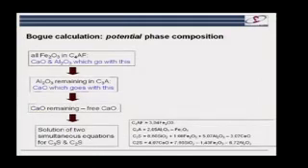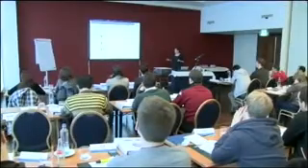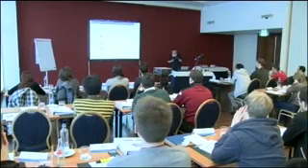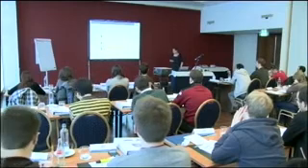And you can express that all in these very complex equations, which take into account the different atomic weights of the different things and everything like that. The problem, as I've said, is this isn't very accurate, because the composition of the phases is not exactly this composition. For example, the ratio of iron to aluminium in C4AF can vary quite widely. In C3S, we can have about 1% of magnesium replacing the calcium, and so on and so forth.